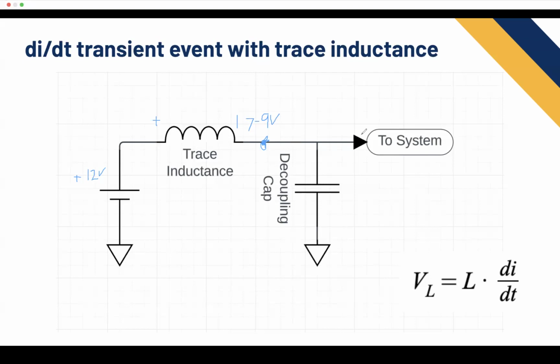If this system over here was relying on that 12-volt signal, and now it just drops, things might start turning off. And let's say that's the battery management system. You don't want that just turning off when it suddenly needs a lot of power, right? Because if you think about it, it just asks for a lot of power. It's probably doing something pretty important. So you don't want that to just shut off. So that's what the decoupling caps are for.